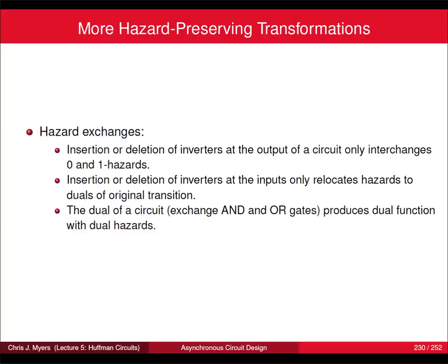The only reason we could get a hazard-free implementation is we restricted ourselves to only the transitions that really happen in the burst mode state machine. Only those transitions do we eliminate the hazard for, right? So if you drew any random transition into a Karnaugh map, you might have a function hazard or something like that, but those would not be the burst mode hazards that you're eliminating. So all functions have hazards under some multiple input change.